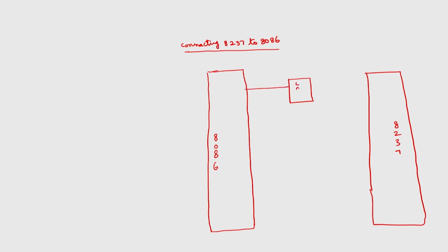This is latch, this will be having two signals, one is called latch enable signal and output enable signal. Output enable is available as active low signal, and this is latch enable, active high signal. This is LE, latch enable. If I consider this AD7 to AD0, the lower order 8 bits of the address, this is multiplexed bus, this is octal latch.